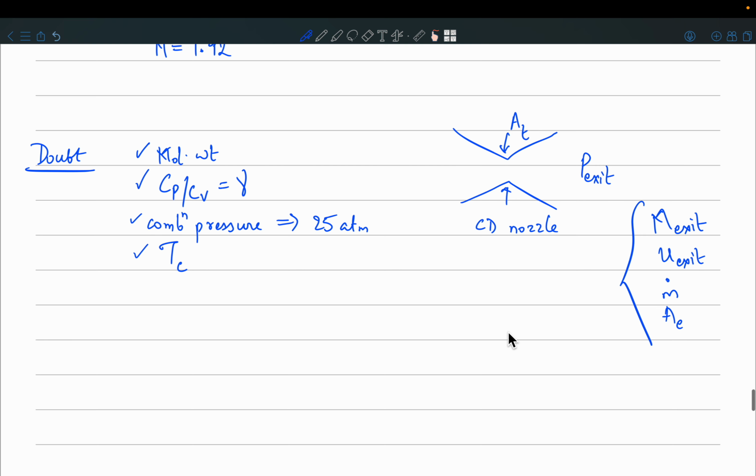Okay, so how you would approach this is, first of all, the most important piece of information that is given to you is that the flow is isentropic. So what does that imply? If it is isentropic, then I can find a reference state, the stagnation state, which is going to be same throughout, isn't it?